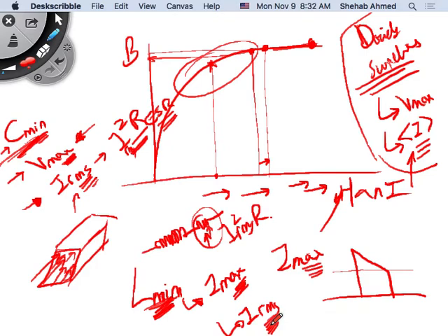So this is how you would down select from your inductors, capacitors, and switches. So everybody's okay with that? So we can calculate the C minimum, L minimum, the voltage across the switch, and the current through the switch. No problem. But then how do you go and buy and select the real one? This is how you do it. Okay?